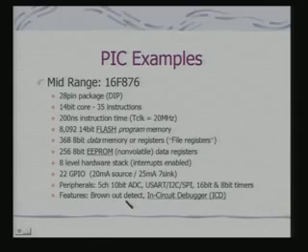What is brownout detect? When there is a voltage level fluctuation, one is power out. When there is power out, I go to the reset state. Brownout detect means that when there are voltage level fluctuations, I can detect that and I can go to a predetermined state. So, this finishes our discussions of the PIC family of processors.